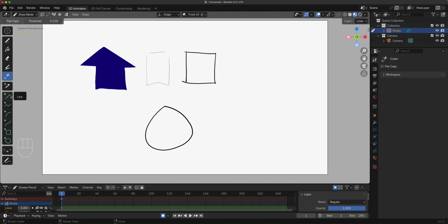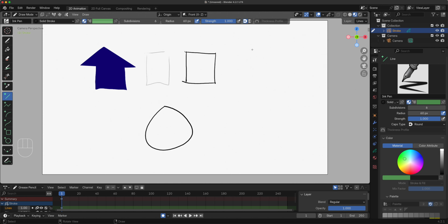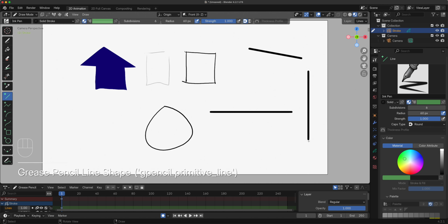Okay, next one would be our pre-made stuff. So if I click on line right here and I drag my mouse, okay, you have 2 points right there that you can still edit. And when you're happy with your line, you can middle click to confirm. It ends the tool. Okay, if I still have that line like so, I can hold down shift to guarantee straight, horizontal, or vertical lines. Middle click, drag to end the tool. Okay, so we have our polyline.